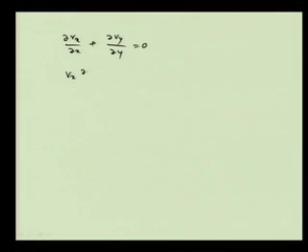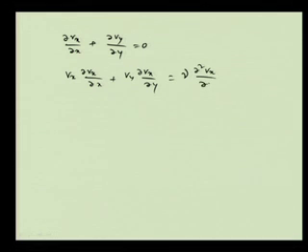So, what we had actually, if you see, is the continuity equation: del Vx by del x plus del Vy by del y is equal to 0. We had Vx del Vx by del x plus Vy del Vx by del y is equal to nu into del square Vx by del y square.